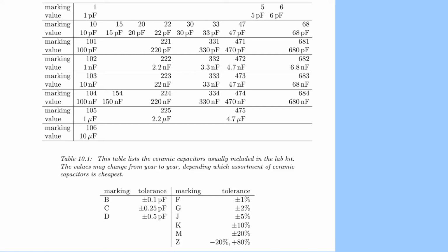The capacitance that we have just from having parallel rows on the breadboard, you've got 2 rows of connectors there, separated by plastic or air insulation. It's a capacitor, and it's going to add 5 or so picofarads to your capacitance. So adding 1 picofarad isn't going to do much of anything. So we're not going to use the tiniest capacitors much, but just about all the ones above that have potential for being used in this course.